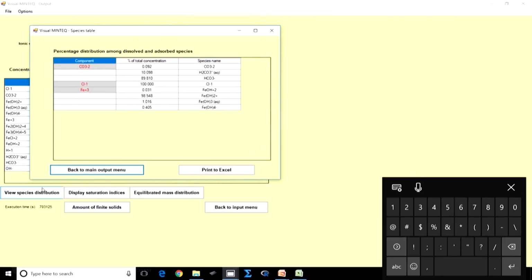Alkalinity means its acid neutralizing capacity, or alkalinity consists of the bases in the form of HCO3 minus and CO3 2 minus. Obviously CO3 2 minus doesn't play a huge role at 7.3 or 8.3 pH values, right, but HCO3 minus should have been at considerable concentrations. So let's just look at that.